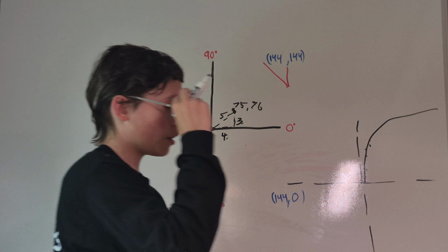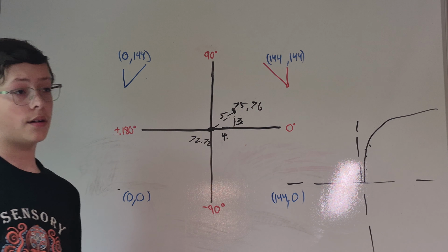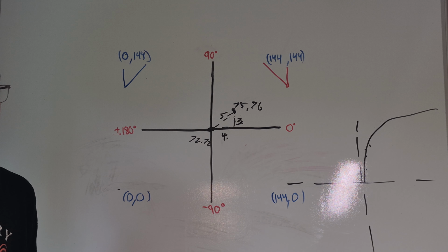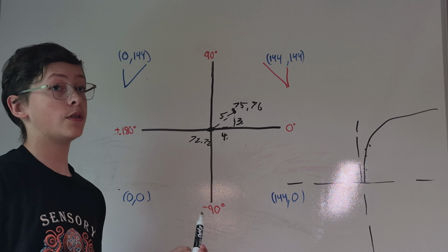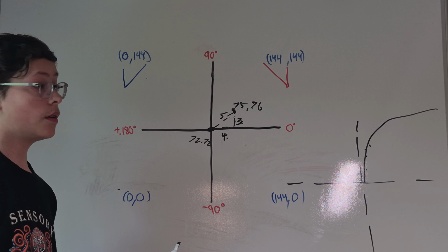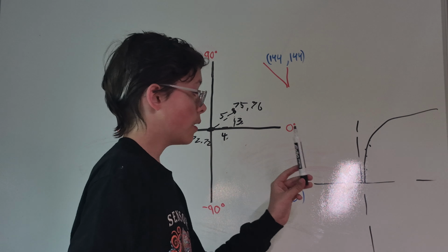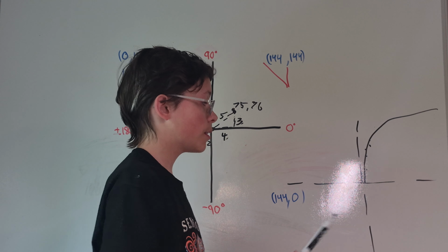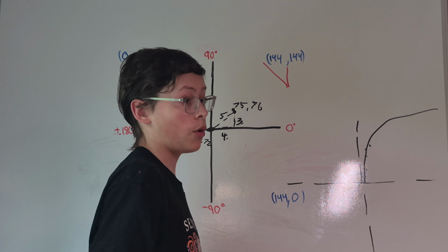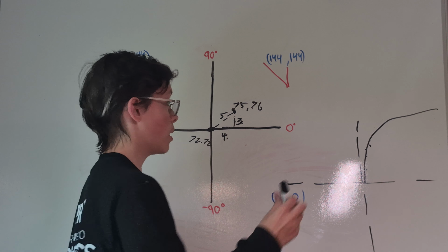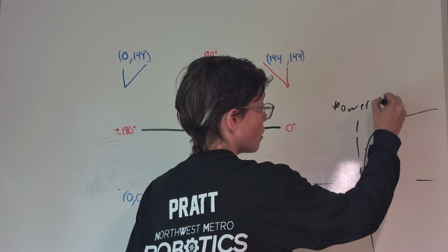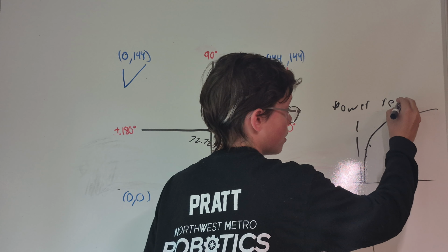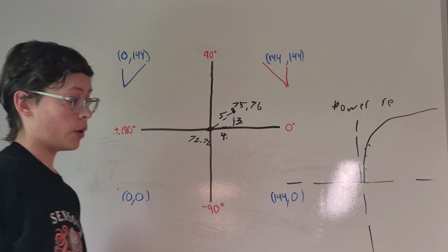This equation does not look linear, because it isn't linear. Since we use 2 motors to run our shooter, it's not linear. But you can find your own equation if you just record enough points. It took a good bit of work. We had to run through a whole bunch of different equations to find the line of best fit. This ended up being power regression. There were a couple close ones, like logarithmic, but their equations were not simple.